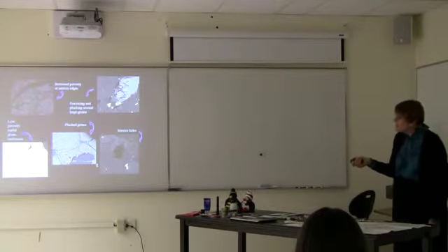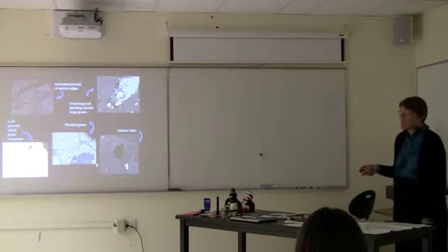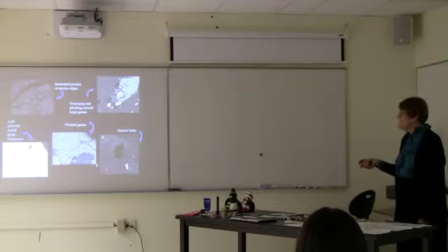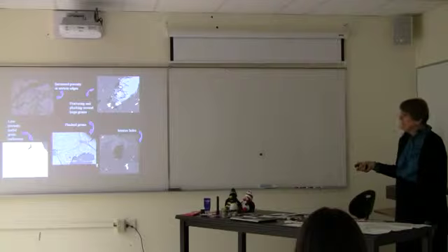But some of these places here I might doubt, because maybe that's damage or shifting when they process that section. There are obvious places where we have big plucks. Grains have been plucked out when they're prepared. I see that, I say that's a pluck, I don't count it. There are interior holes, however, you have to be careful to differentiate the holes from the plucks.